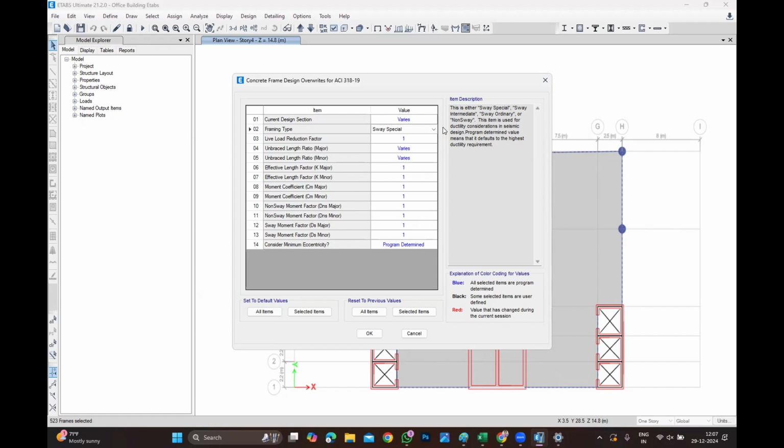Maybe instead of 10, I have to go for 13 rebars, and 3 rebars you have to add. Correct? So why don't you take these 3 rebars till the foundation? You're not doing that, right? What you used to do is take only 50 times the diameter, right? So the bar is floating, right? Now I'm telling the terminology.